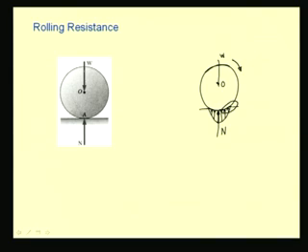So, the material here compresses and thereby offers more reaction, and the material here is relieved because the wheel is moving away from this portion. So, what happens? The distribution here, the material gets relieved and here it gets compressed because of this motion.